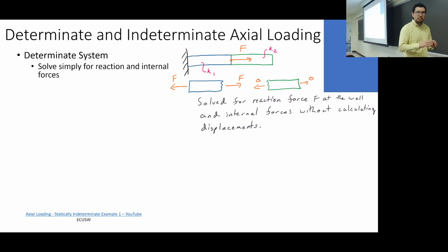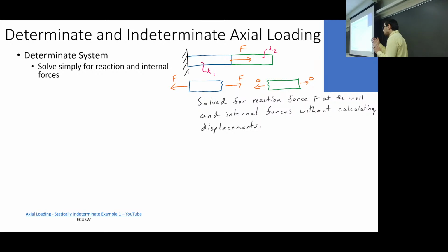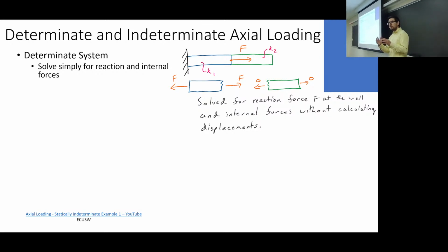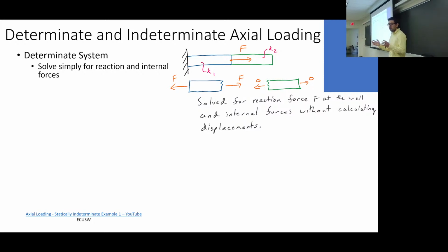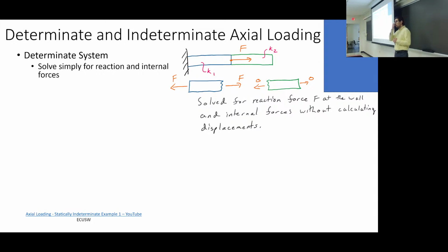And we'll cover this a little bit more, but this idea of relating forces to displacements is something that in mechanics we call constitutive relationships. It's a fancy word. Okay? And you'll see it come up when you do multiphysics simulations, if I'm teaching it, we'll talk about it. Okay? If you take DMC, we'll talk about it a little bit, but these are constitutive relationships. So we've kind of introduced K as your first fundamental constitutive relationship, if you want to be fancy and write home about it. Okay? So a determinate system doesn't need anything related to constitutive relationships.